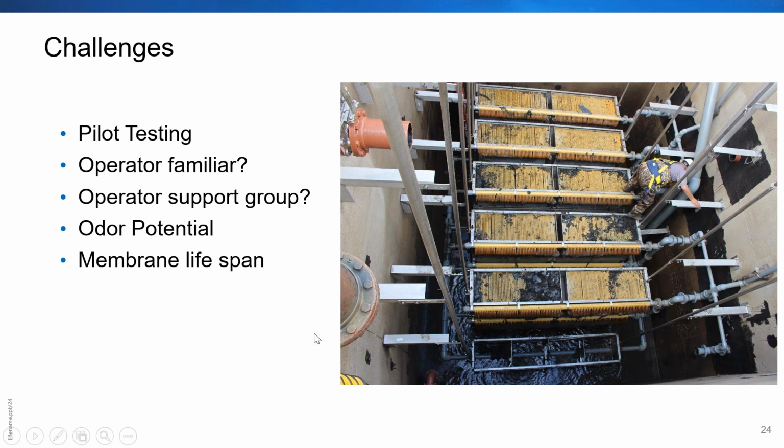And then lastly, pilot testing. There doesn't seem to be enough of it out there. Of course, pilot testing is going to be very plant specific and area specific, because each waste stream is different, especially on the industrial side. Pilot testing would be highly encouraged, kind of like we did about 20 years ago on the MBR side. We almost need to go back to those concepts to see how it's going to work out for full scale and understand better about the kinetics.